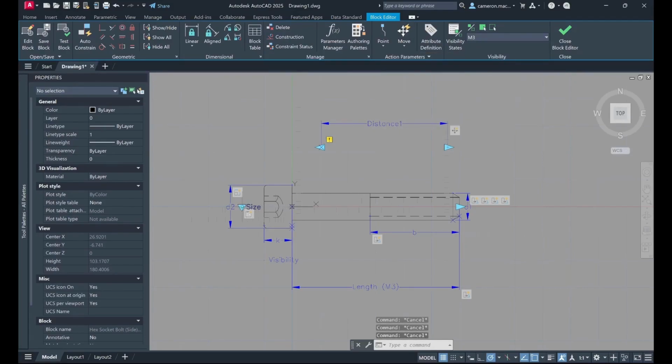We also have a lookup functionality, which can then decide that we need to look at various visibility options within the model itself. So if we were switching between an M10 and an M5, we can toggle visibility of certain parameters on and off, or certain types of geometry on and off at the same time.